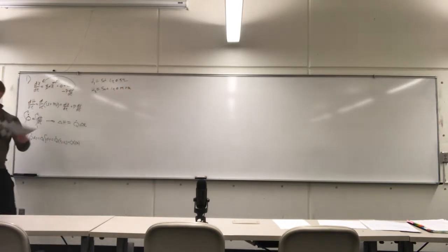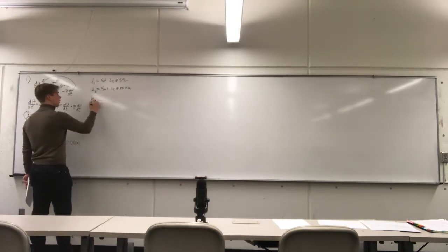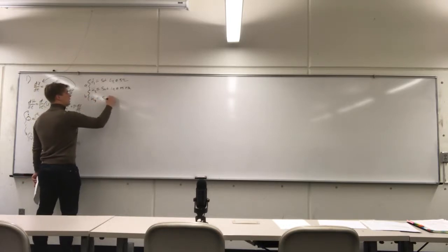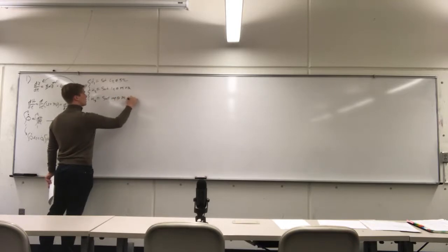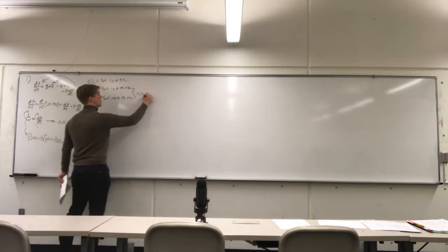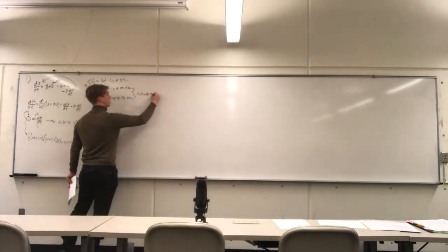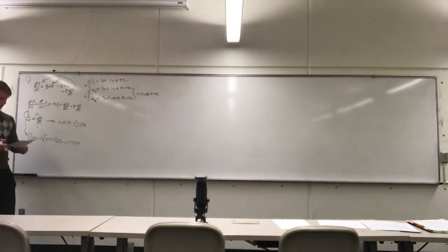Right, we're not boiling at the normal boiling point, we're boiling it a little bit lower. And then for part B, state 3 was a saturated vapor at 75 kilopascals. So the step between was the delta H of vaporization at 75 kilopascals and whatever the saturation temperature was under those conditions.